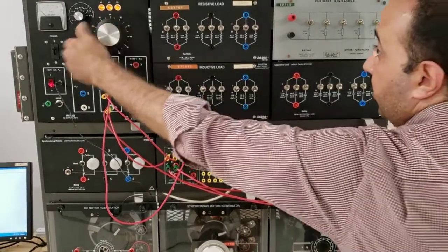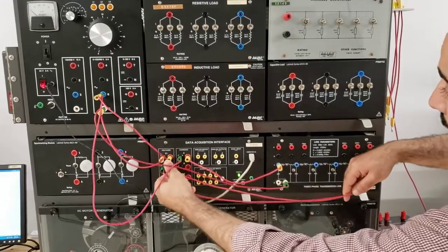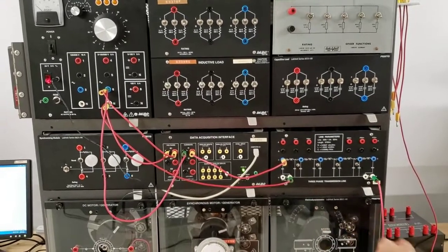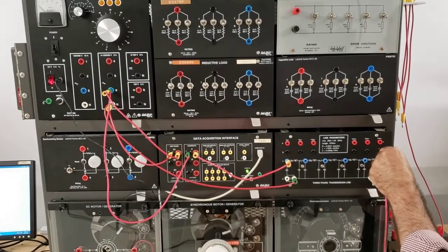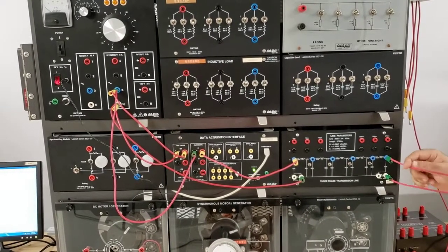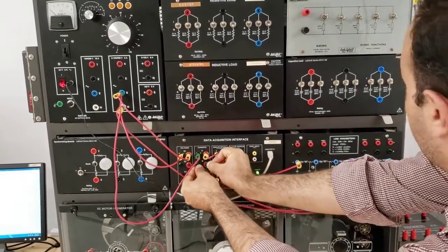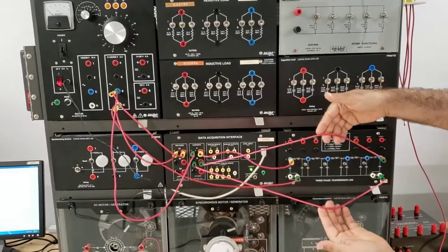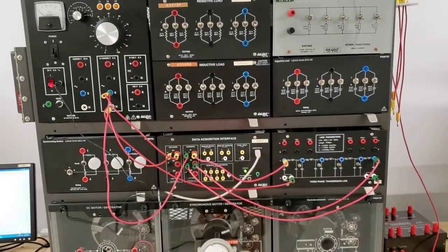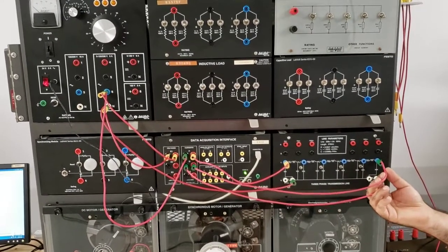For the second part, which is the short circuit test, I'm going to repeat the same story, but instead of leaving this guy open, I'm going to add the short circuit here. So this guy, I didn't make any change. This guy will be the short circuit, but I would like to measure the short circuit current. That's why I'm using 2 wires, because I will connect this guy here to measure the current in series. And I repeat the same story. I will try to change the value of the voltage and measure the sending end voltage and the sending end current, and at the same time the receiving end current.